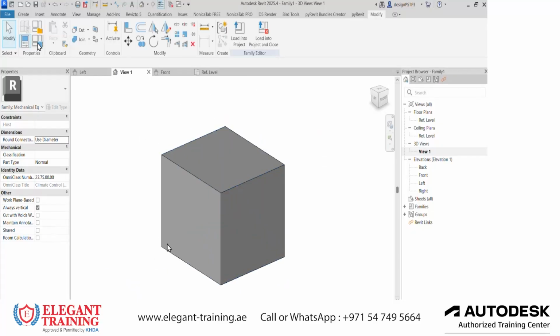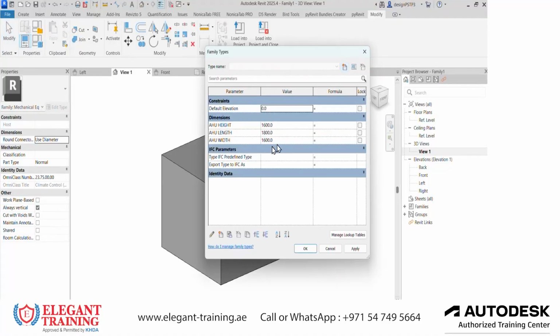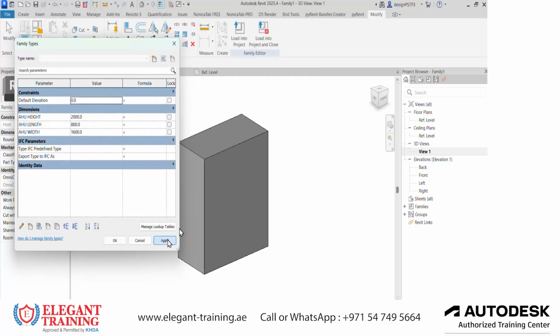In family creation, to check that the constraints are moving, you can choose family types. Once you choose family types, you can control the parameters you made here. For example, the height, if you need 2 meters, it's changing here. Then if you need 800 for width, or 1500, and height also if you need 16, that means the parameters are ready.